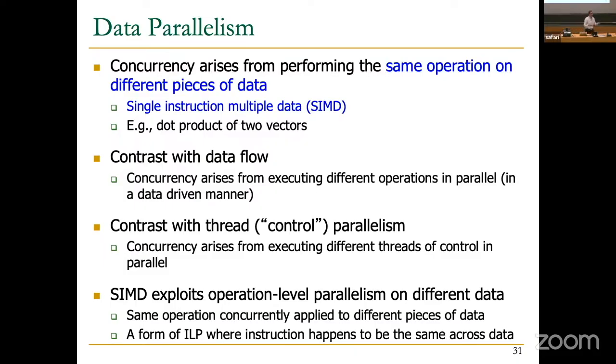So imagine that you're actually adding 2 vectors of 1 billion elements. In a scalar processor, you would be decoding the same instruction, add instruction, 1 billion times, fetching and decoding. In this case, we're going to see you fetch and decode the add instruction only once, and it's going to control 1 billion data elements to be added. So that's where the efficiency really comes from.